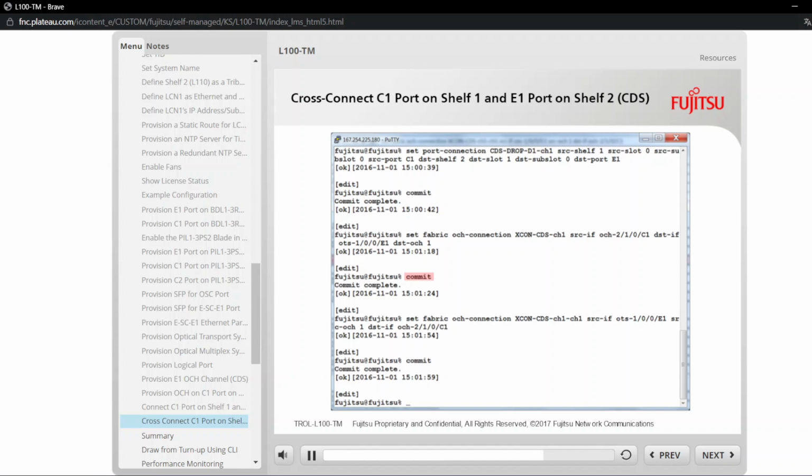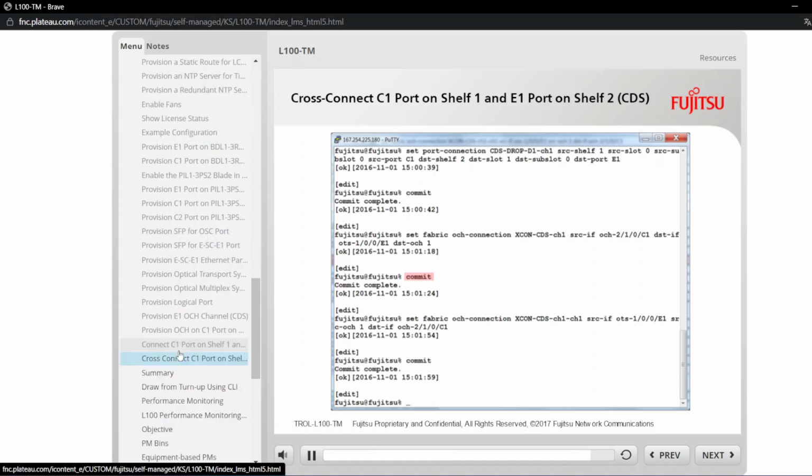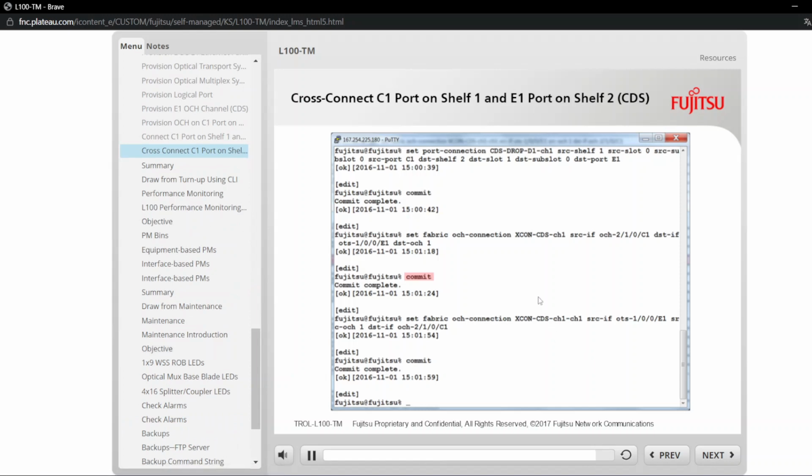The FlashWave CDS now has a service path through the L-series equipment, and it has service, assuming its database has been provisioned. To provision the service for the Onefinity T310 shown in the example network earlier, repeat the actions from the last 3 slides, with different parameters for the following: OCH number and center frequency, OTS number. Client port references should be for C2 instead of C1.